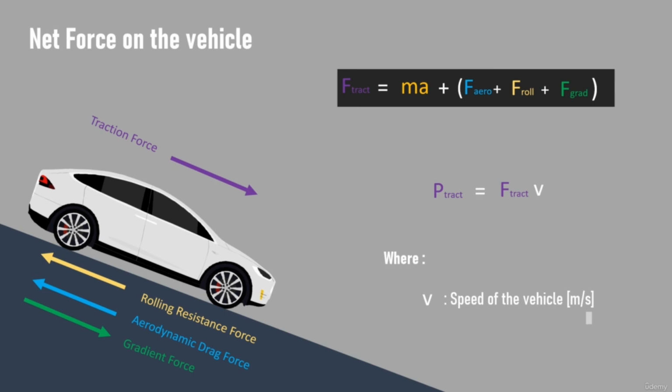It is important to realize that in this lecture, we only take into account the forces in the forward and reverse direction as they influence the powertrain. The forces in other directions are neglected for simplicity. Secondly, the forces in the vehicle are assumed to be acting at one point. In reality, the forces are distributed over the vehicle.